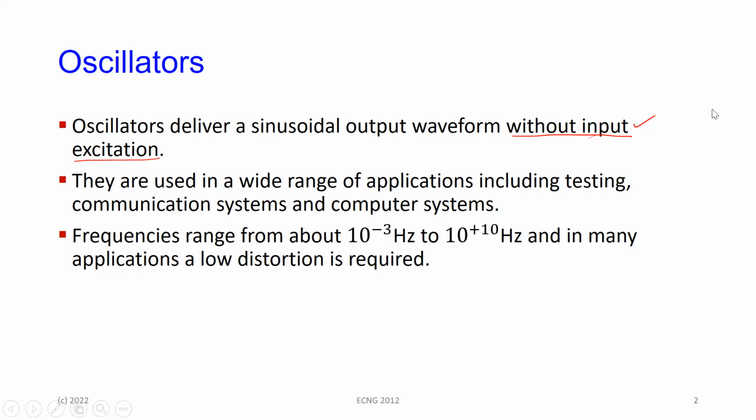What that means is that, as you have done in Fourier series, depending on what the signal looks like, it has harmonics, which are not only a fundamental frequency, the main frequency, but multiples of that, and we'll talk about that. But every time you have harmonics or extra signals around there, the signal is experiencing distortion. What you want in oscillators is to generate a signal that is as clean as possible, with very few harmonics around. That's what they're talking about here.